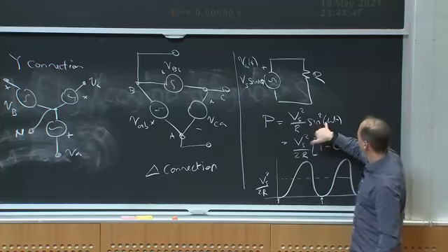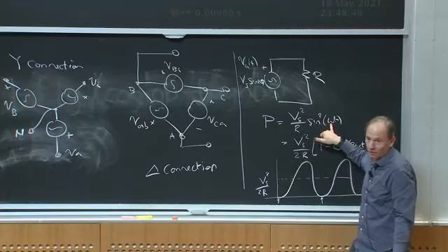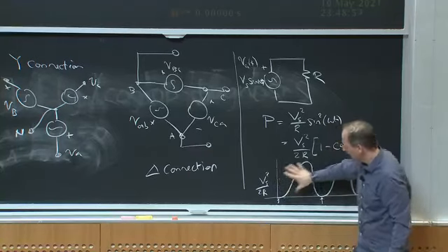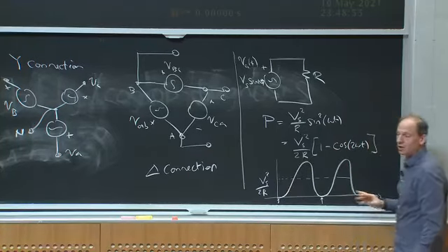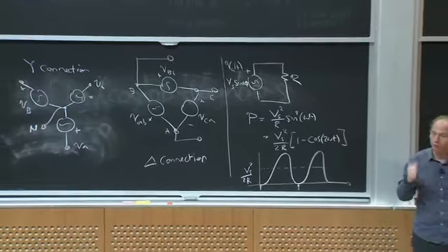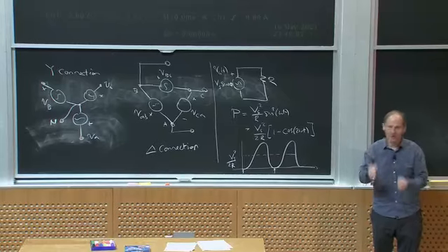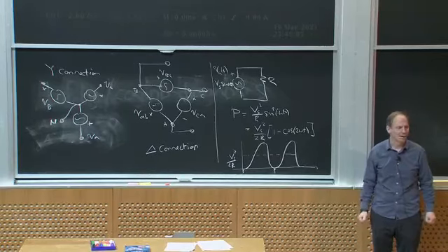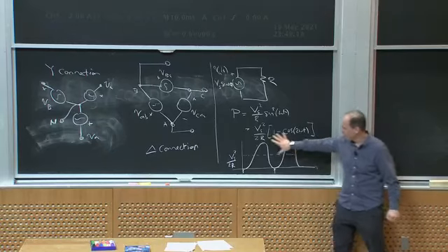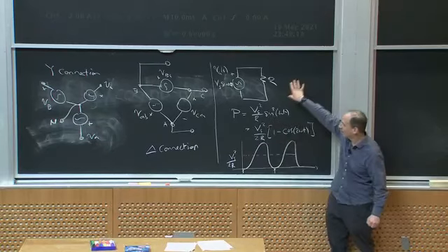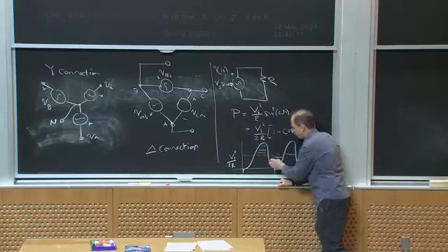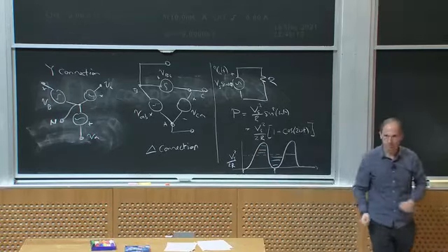Every zero crossing is because the voltage went through 0. When I've got 0 voltage, I'm not getting any power transfer. So no matter what I do, I'm going to have this pulsating power. The way that reflects itself is, even with a single-phase motor running at constant speed, I'm going to have torque ripple at twice the line frequency. Or if I have a rectifier and I want to deliver constant power somewhere else, I'm going to have to buffer these energy pulsations, so I'm going to have to put energy storage out there to do that.